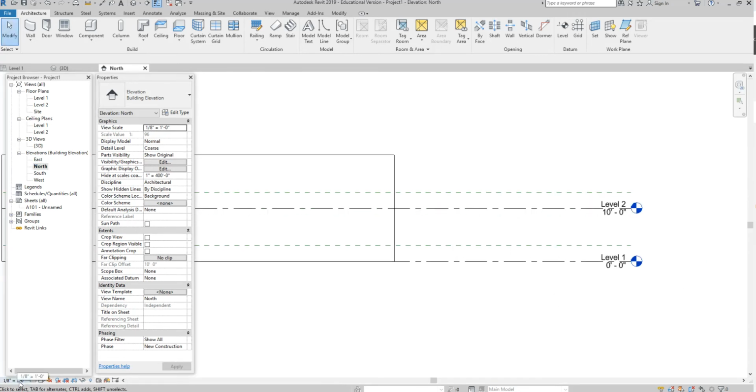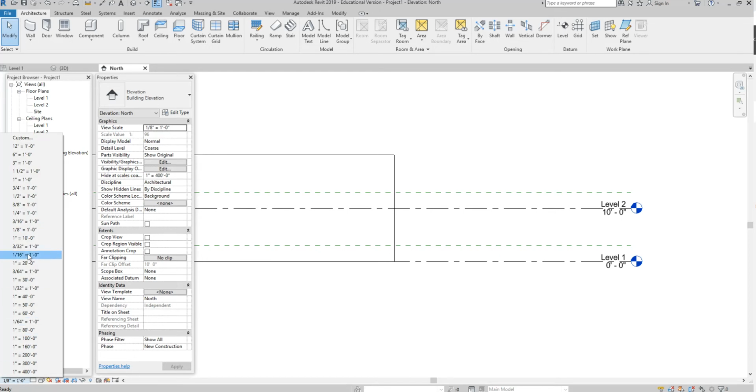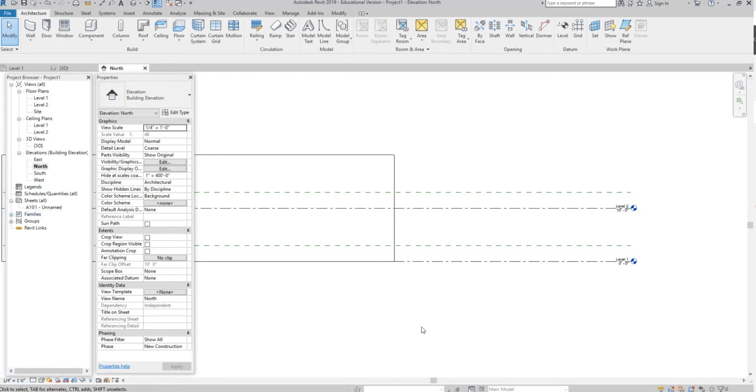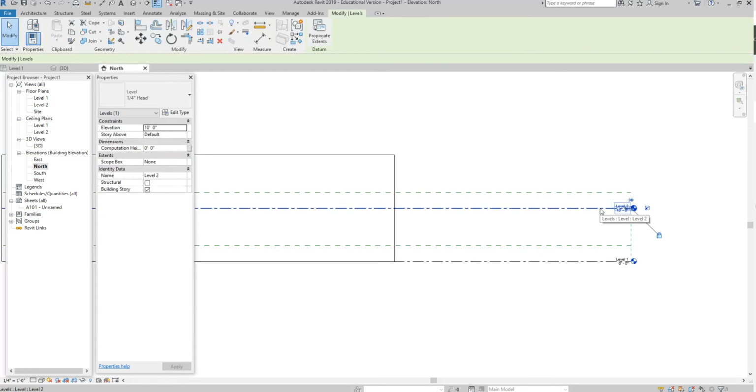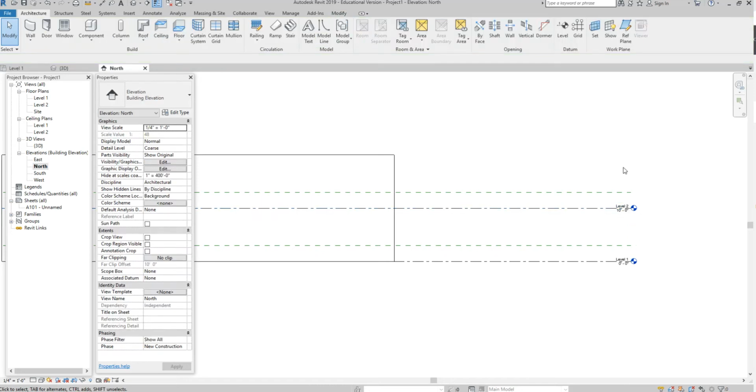It changes the scale. So if I click on this, I can change to 1/4 of an inch. The magic just happened right there. My annotation also went to 1/4 of an inch scale. This again is one of those aha wonderful moments for those of you that have used AutoCAD. Look how nicely the annotation changes when I change the scale of my Revit drawing. It's just all automatic, it's all built in. There's no going back and having to alter any type of annotation, which is wonderful.